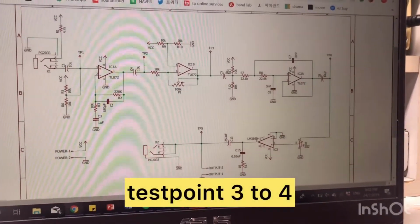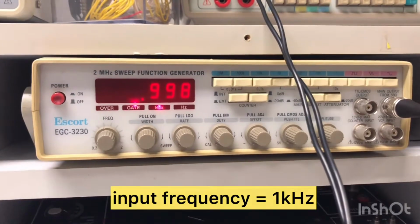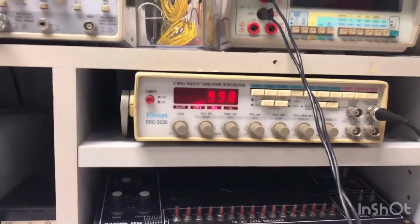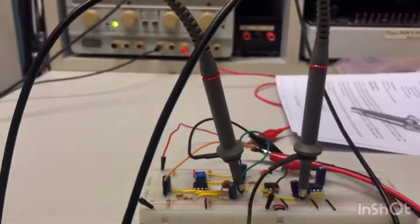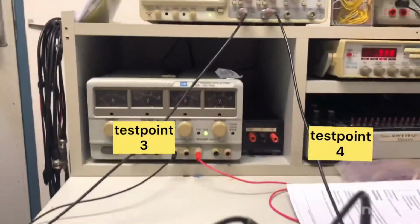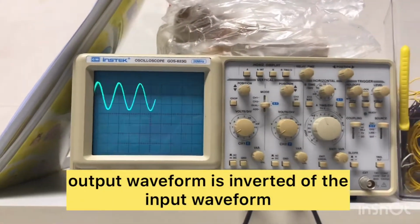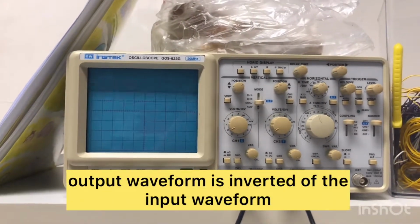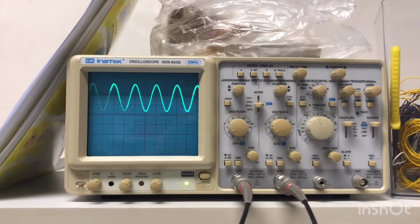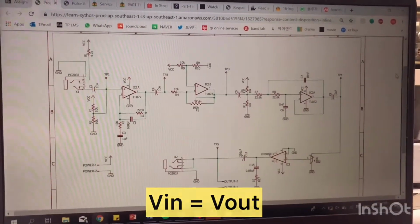Now I'll be testing test point 3 to test point 4. The frequency is set to 1 kHz like the previous lab. Channel 1 is connected to test point 3 while channel 2 is connected to test point 4. Here you are able to observe that the output waveform is the inverted version of the input waveform. The output voltage is the same as the input voltage.